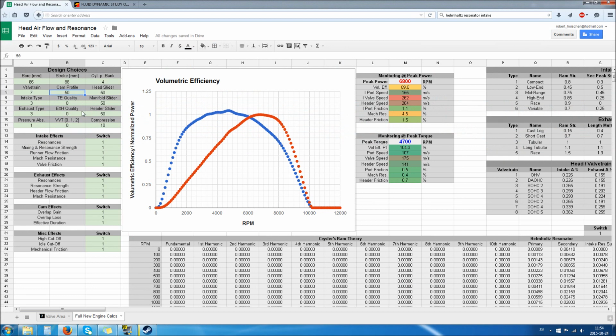That would be building 3 different engine types with these different parameters we have up here. And because we are all set to some kind of standard size here already, why not start out with a mid-range engine, which we already kind of have here. So if the volumetric efficiency goes above 1, that means that into 1 liter cylinder capacity, you fill in more than 1 liter of air, and that can be achieved by not only supercharging or a turbocharger, but also via acoustic resonances.